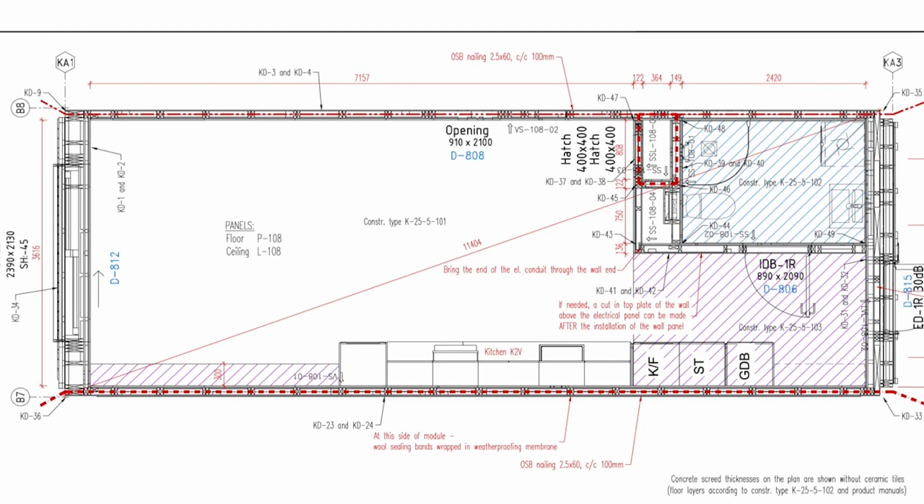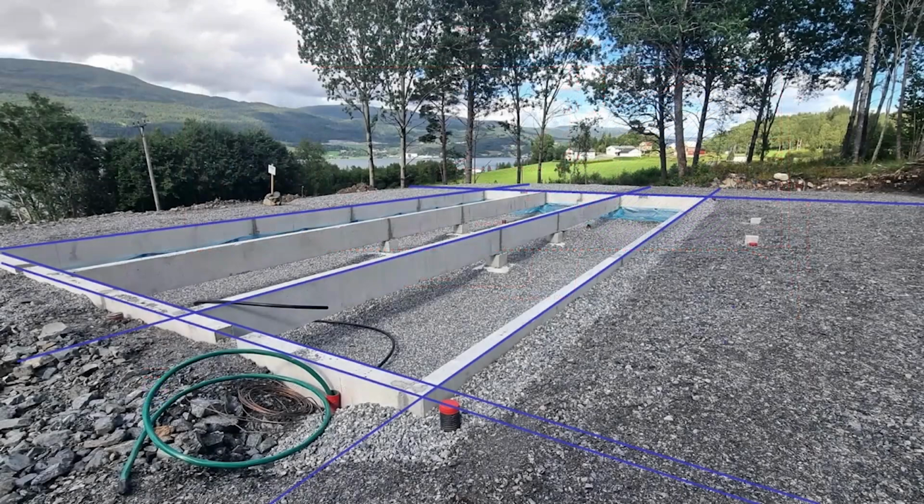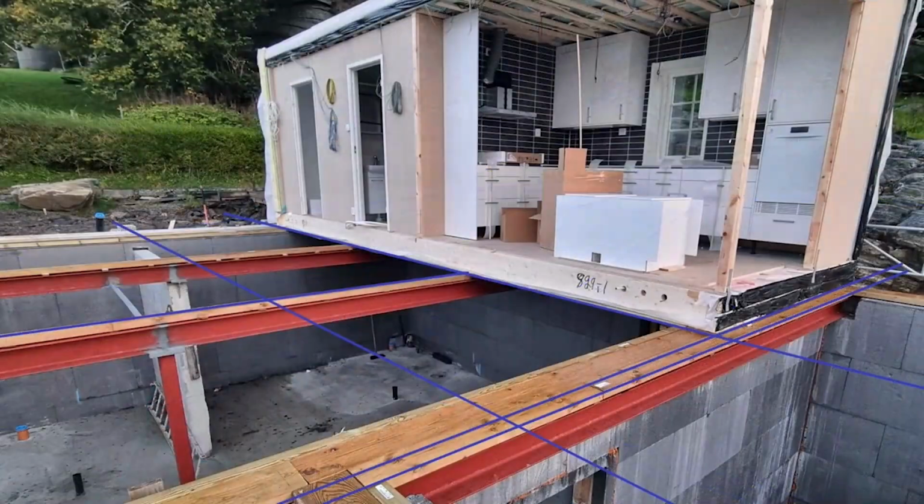You can refer to a part of the building that is on an axis, where two axes cross, or between axes. In the case of external walls, the axes are marked on the outer surface of the outer walls, while at the joints of the modules, the axis shows the conditional center line. The axes of the building are also necessary in order to mark the building down in nature before the start of construction work.